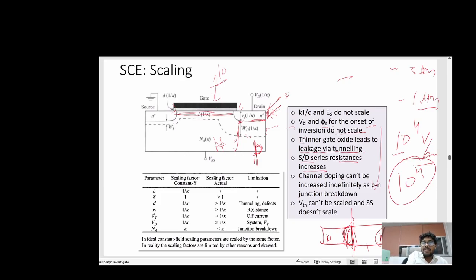So to make it N type, to create the channel will be very difficult if you increase the doping here. So in that case, what we need to do is let it be as it is, P and A. But we can reduce the doping in this one so that we can reduce this width.